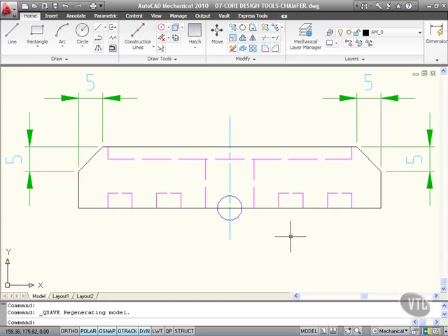So let's look now in more detail at our chamfer core design tool. I've zoomed in a bit closer now on our side view because we need to tidy up these grooves here. These are actually grooves in our side view. So what I need to do here is tidy up these. They're not actually fixed rectangular grooves like that. They do actually have chamfers and fillets on them, so we need to tidy up a little bit. Also, these corners here need a small chamfer on each corner as well.